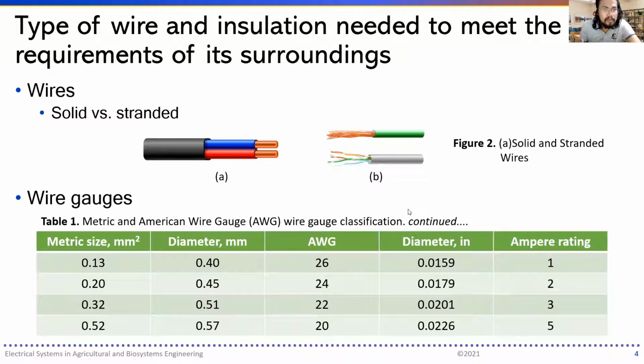In the wire industry, there are so-called solid conductors, and they tend to be hard to bend as they get bigger in size. Now, smaller strands of wire twisted together can equal the same effective area as a solid strand, and that is why there are also stranded wires.